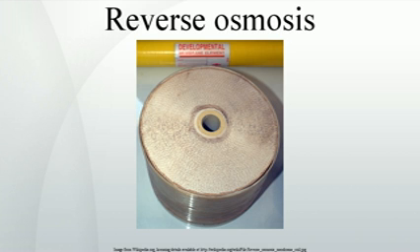Within the United States Marine Corps, the reverse osmosis water purification unit has been replaced by both the lightweight water purification system and tactical water purification systems. The lightweight water purification systems can be transported by Humvee and filter 125 US gallons, 470 L, per hour. The tactical water purification systems can be carried on a medium tactical vehicle replacement truck, and can filter 1,200 to 1,500 US gallons, 4,500 to 5,700 L, per hour.